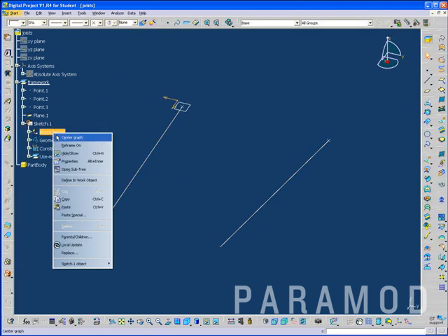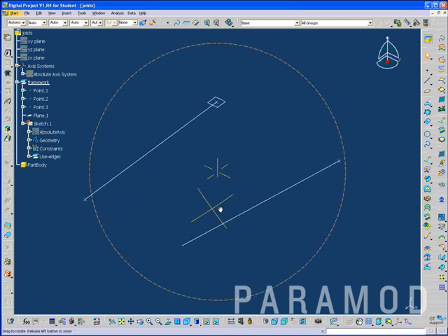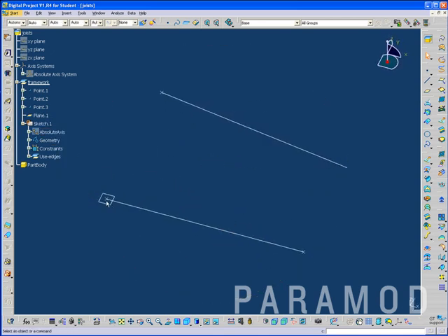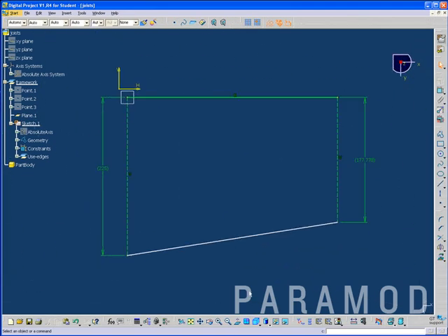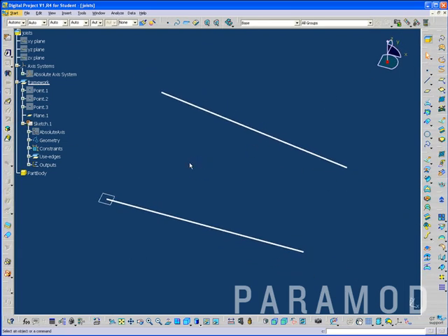I like to turn off the absolute axis for the individual sketches. And so since this is the line that we'll be using to set our power copies, the other line will become the line that we use to reference that. And so actually what I'd like to do is I just want to go into the sketch and create, again for best practice sake, make each of these an output feature so that we don't have any problems about referencing them separately when we're outside of the sketch. So now we've got that.